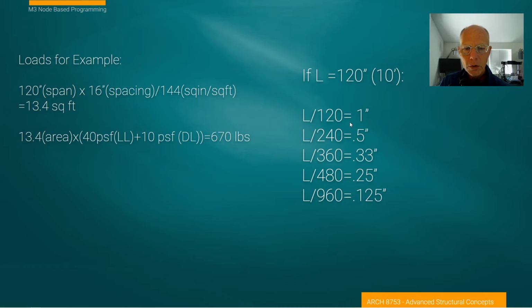But then we can take that and look at these L values. I calculated this number, 670 pounds, because I want you to also think of that in relationship to a person walking across the floor. In that section of floor, if somebody was walking across it, creating a kind of dynamic on the surface, they would be representing maybe 20% of the calculated applied load. So when we look at these deflections, we're not saying that if somebody stands on the floor, it's going to deflect a half inch. It's going to be much less because it's a small component of the full load for that rated deflection.